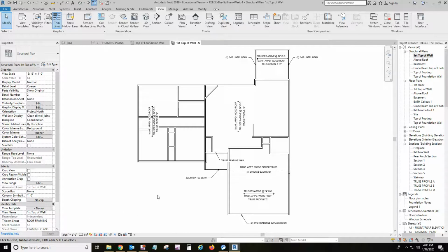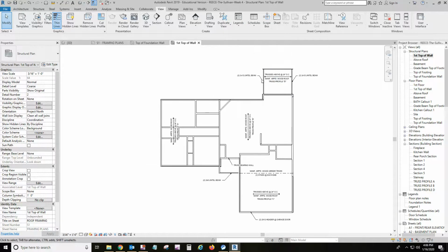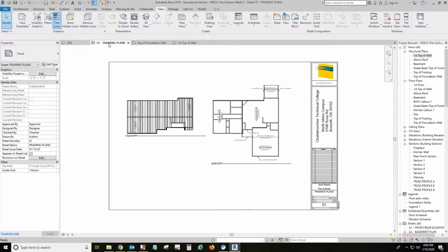Okay, I'm just trying to plug my view range to get my walls looking right, but that looks okay the way that it is. The main thing we're trying to do is show what trusses are going in what area, and then where we've got lintels and where we've got beams. And of course, that's set at 3/16 inch. Renamed it here, roof framing, and then I pulled it into my structural drawing there. Okay, and so that's got our structural plan.